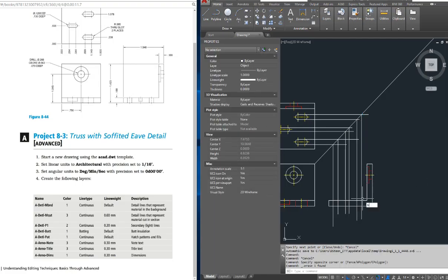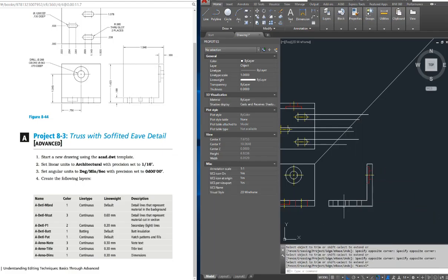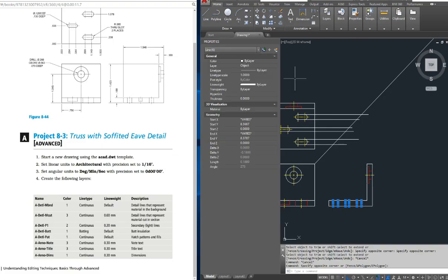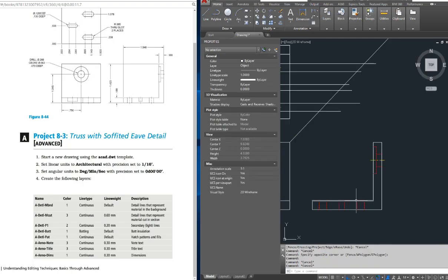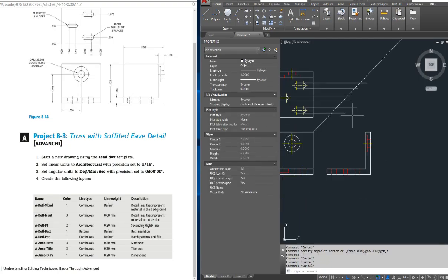Doesn't look like much, but when I say trim, select these 2 as my cutting edge and trim those out. Select those lines in the middle and say, I really think you should be hidden. Look at that. There they are, my 3 holes. Now, that's not quite finished yet. This one here, this small one, has a depth of 0.130.